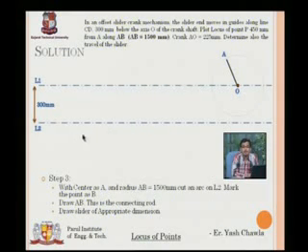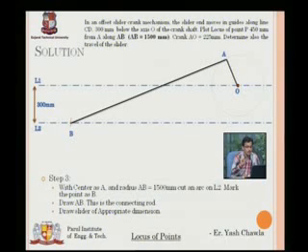So I will have the different positions of the slider on L2. With radius equal to the connecting rod and center A, I will cut an arc at B on line L2. This is the initial position of the slider. Again, I will draw the connecting rod AB, and then make the slider of appropriate dimension, which is not mentioned in the question.